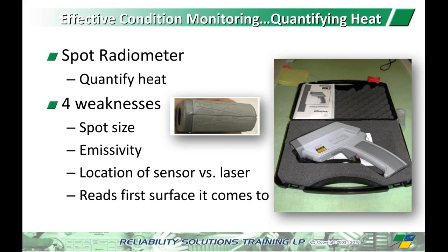What's my operating context? And certainly if you've got a pressure compensated pump, which varies the flow rate, and you're dropping a significant amount of heat across a relief valve, that's a flag. That shouldn't be happening, because your pump should be going off stroke to reduce the flow. And how many times do we get reports that my hydraulic system runs hot and